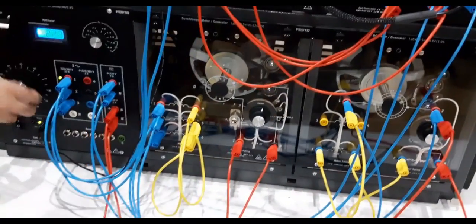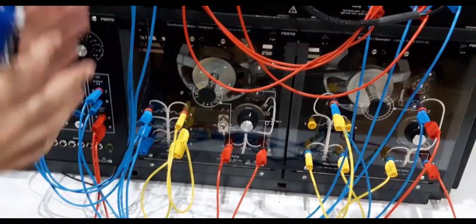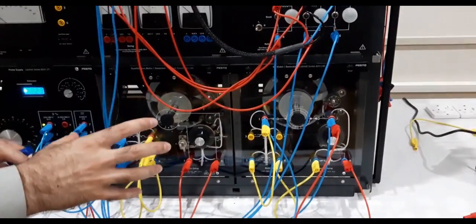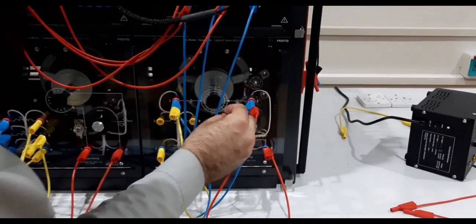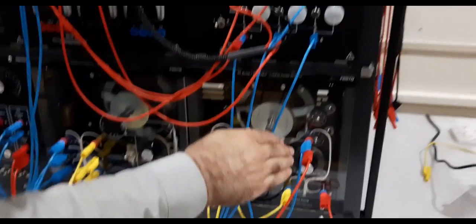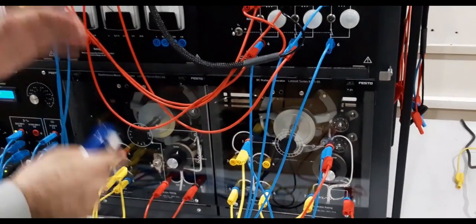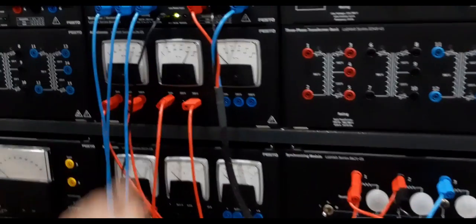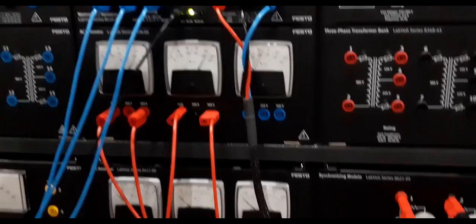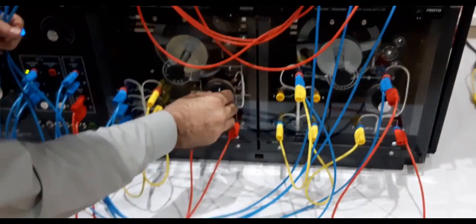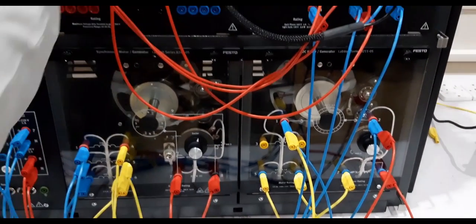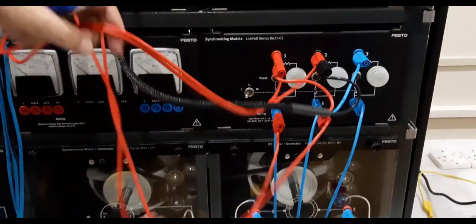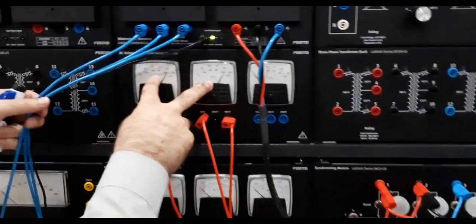So we demonstrated to you that in the beginning we increase the speed of the shaft by increasing the voltage, and once we achieve a voltage closer to the rated voltage, we further increase the speed by decreasing the field flux, by decreasing the field of the DC shunt type DC motor, because by decreasing the flux the speed will increase. And we also demonstrated to you that the voltage of the generator can be varied either by changing the speed or that of the main field of the machine. So we also changed this field, and then we brought the voltage of our generator close to that of the system, and we demonstrated to you here.